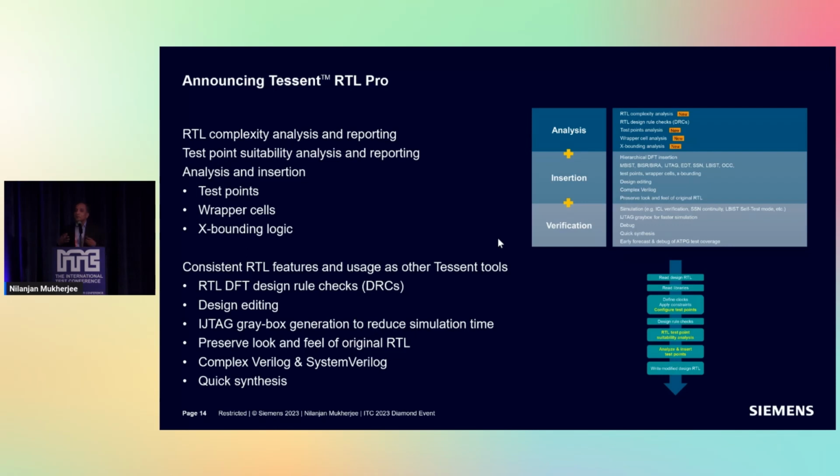It does a quick RTL complexity analysis and reporting, so you know what some of the complex RTL modules are that you have. It also does an analysis of the RTL to let you know whether that design is suitable for test point insertion in RTL or not.